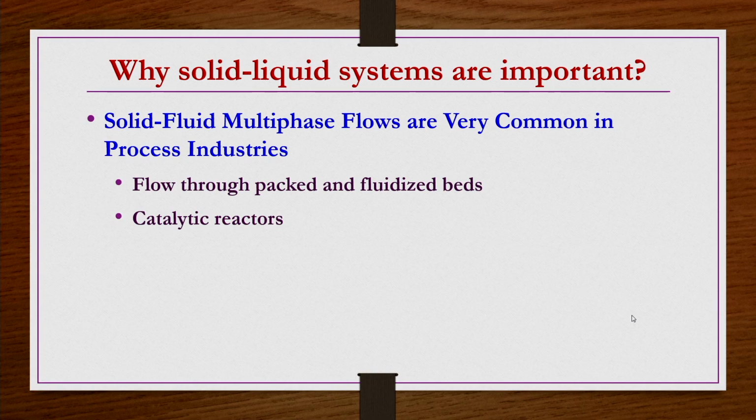We have filtration, etc., operations in mechanical unit operations, where we will be using the principles of flow through packed beds. Then we have several catalytic reactions in chemical and process industries, wherever catalytic reactors are there. The solid catalytic phase is interacting with the surrounding liquid phase, with which it is going to undergo a reaction process. So, under those catalytic reactors also, there is a relative flow between solid and fluid phases.